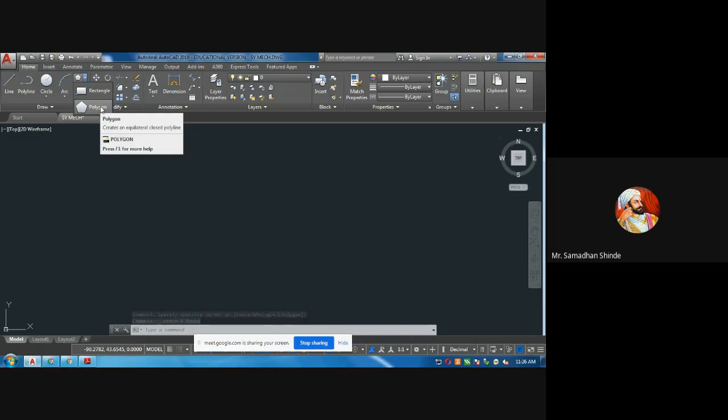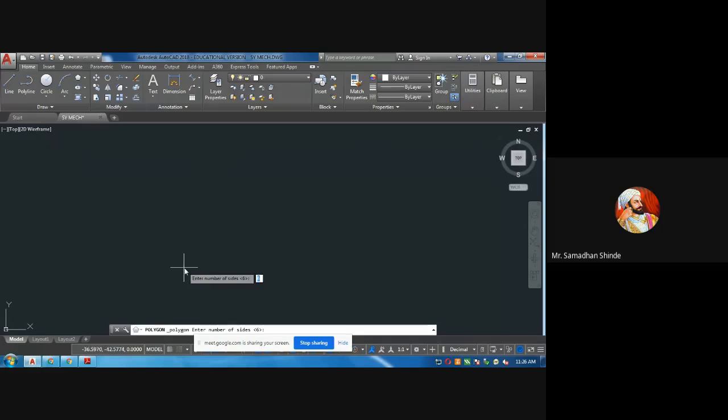So similarly, you can now tell me, I want a pentagon of 50 mm side. So what can be done? Select polygon, number of sides 5, enter. Instead of center, we are not interested in circumscribed or inscribed. So what we have to press? We have to press E. E for edge. Edge, enter. Select first point. Select second point. Suppose 50, I want side as 50. Enter. Like this it will come.